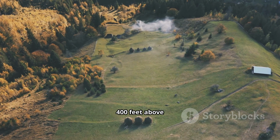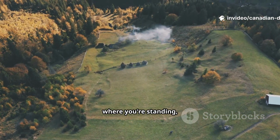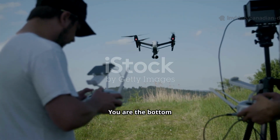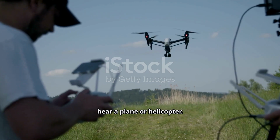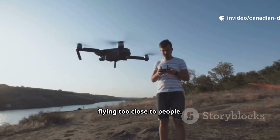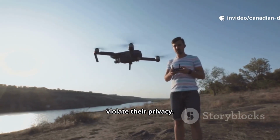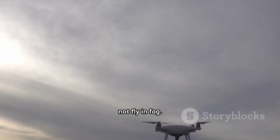Maximum altitude, 400 feet above ground level, AGL. If you're on a hill, it's 400 feet from where you're standing, not from sea level. Give way to manned aircraft, always. You are the bottom of the pecking order. Land immediately and safely if you see or hear a plane or helicopter. Do not fly recklessly. No flying too close to people, animals, or property that you endanger them or violate their privacy. Stay out of clouds. You must remain clear of cloud and not fly in fog.